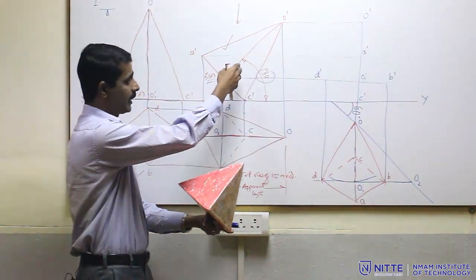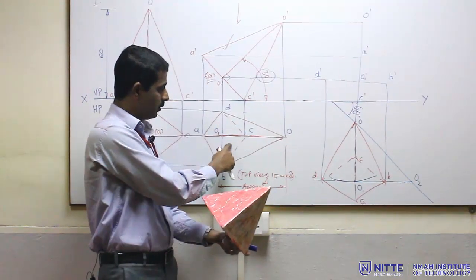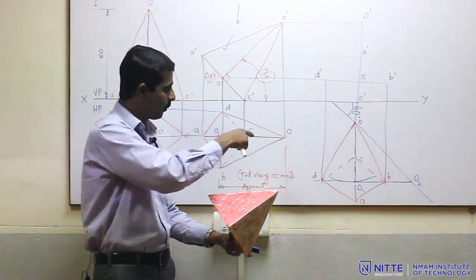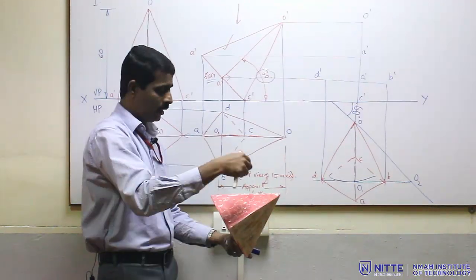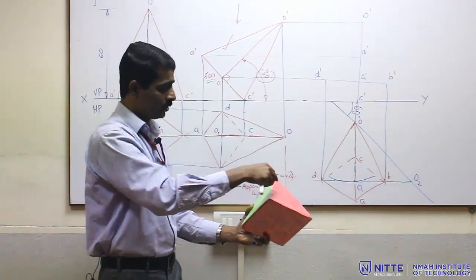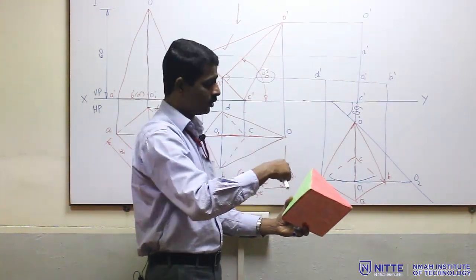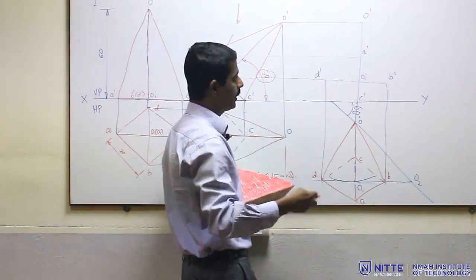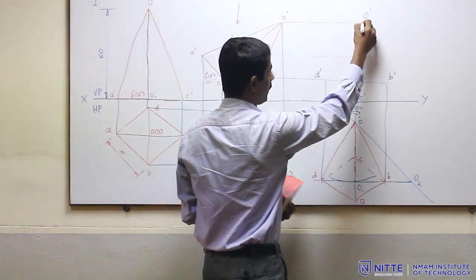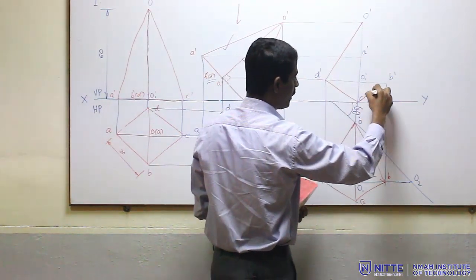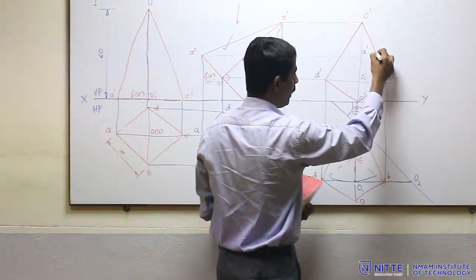So in this view it is the same, and when we projected the top view, okay, this was the boundary OD AB and the visible edge is nearer to the observer. Now it is rotated this way, okay, so again we have a certain boundary. So boundary is nothing but connecting the outermost points. So let me connect the outermost points, which are O dash to D dash, D dash to C dash, C dash to B dash and O dash to B dash.